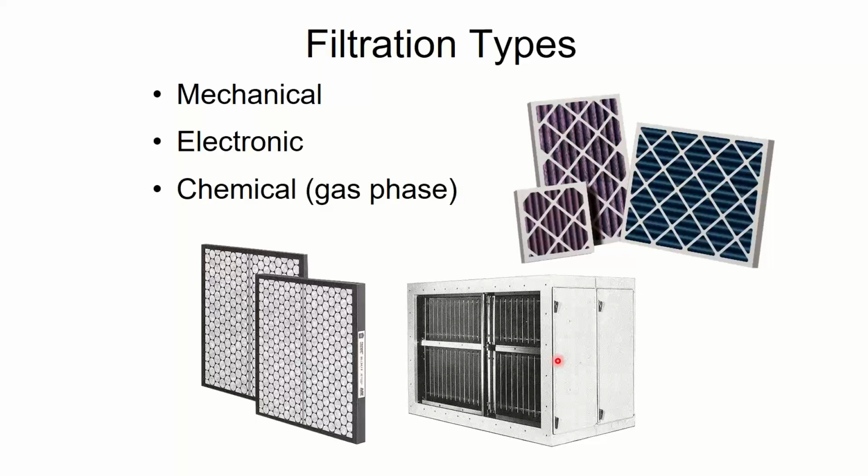The bad thing about electronic filters is that once the plates get covered in stuff, they do a really good job of catching stuff. But once they're covered, now I got to clean them off so they can catch more new stuff. And the problem with electronic filters historically has been people don't clean them. Or they clean them the first few times, first couple months, and by year 2, they've stopped dealing with it. It's fine. Okay. They ignore it, right? And then it doesn't do anything anymore. And it's a bad filter. It doesn't keep your coil clean. It doesn't keep your air clean.